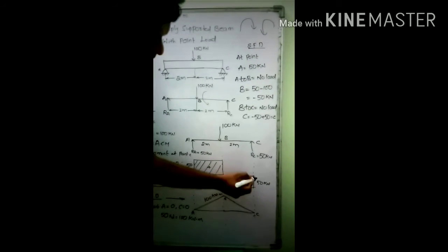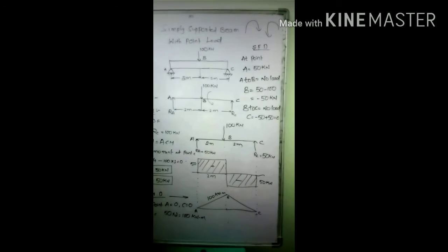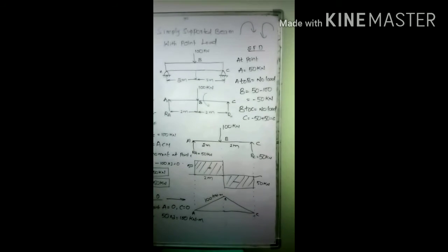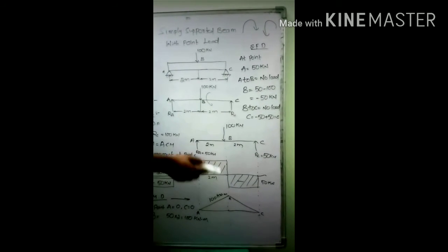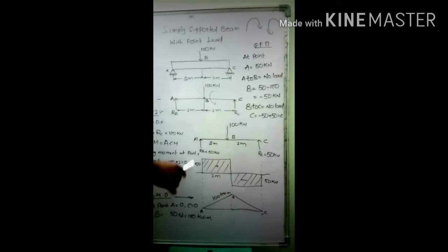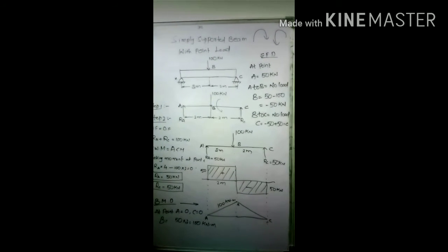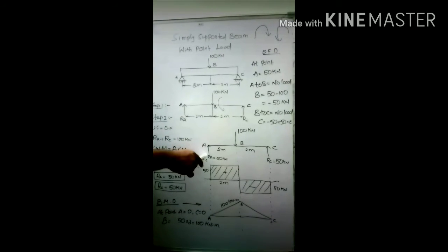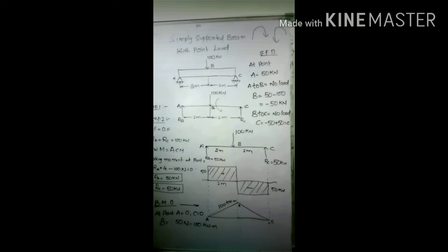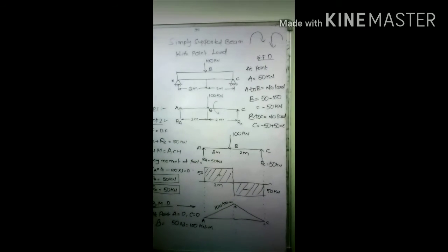the reference axis. For the reference axis, values above are positive and values below are negative for a shear force diagram. I am considering it like that only. And my consideration is that upward force is positive and downward force is negative. I already told you this convention.